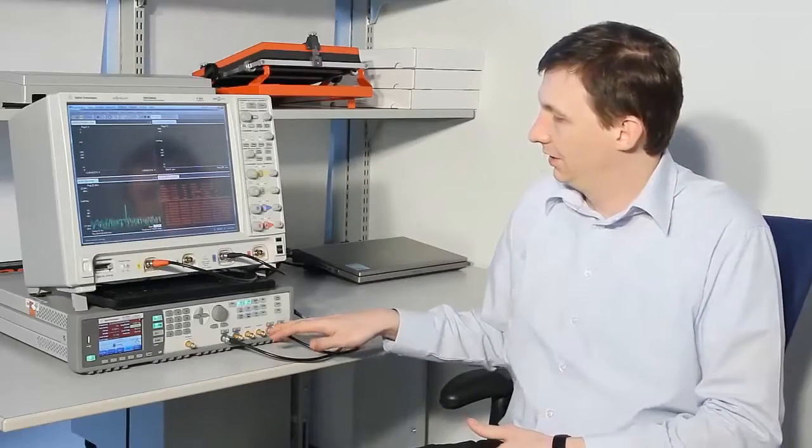Why would we need coupled channels? There are some applications where this becomes essential. For example, creating IQ signals via two synchronous channels. One channel would be used for the I part of the signal. Another channel would generate the Q part of this complex signal without any skew between the two complex parts. After that, you can start adding distortions to the IQ signal, such as amplitude mismatch or quadrature error.